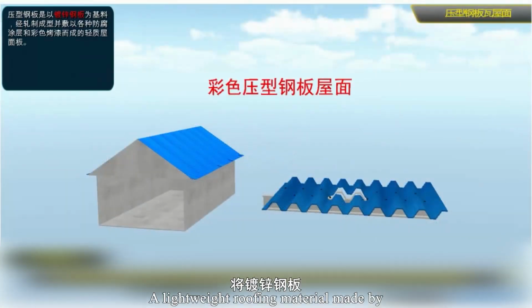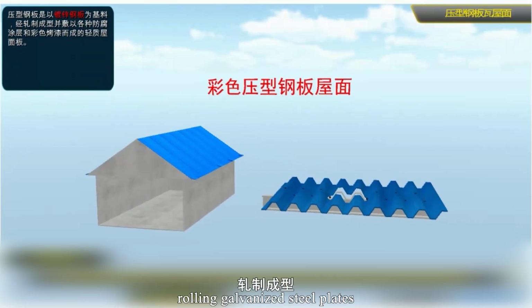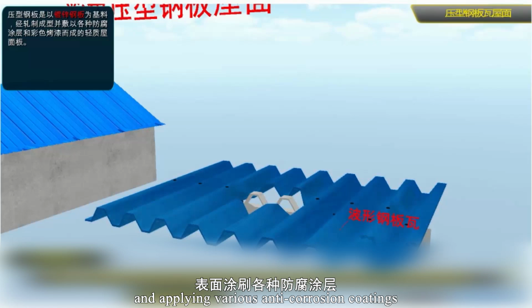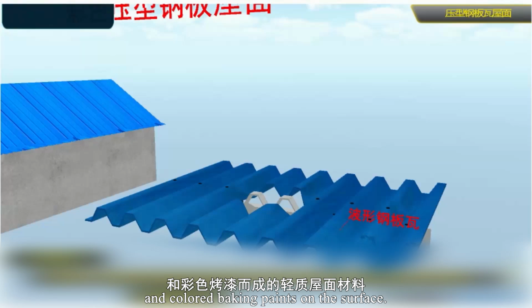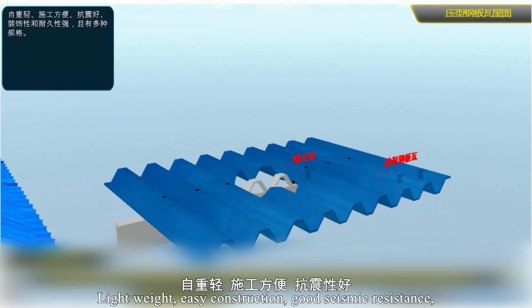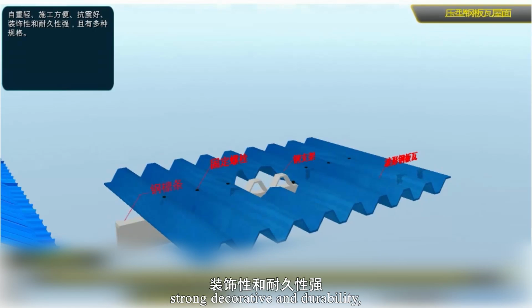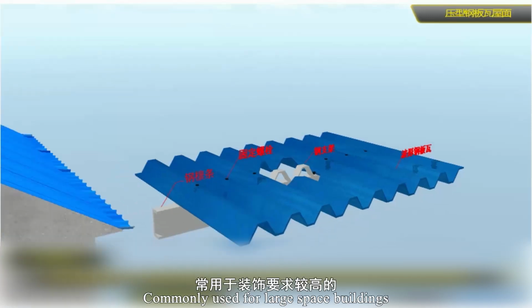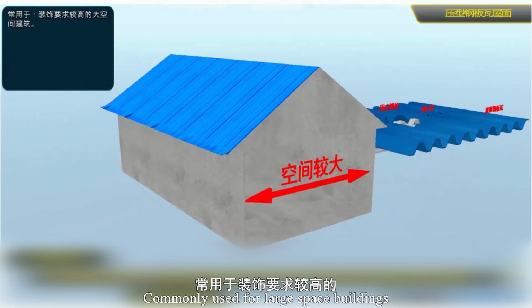Profiled steel sheet roof. A lightweight roofing material made by rolling galvanized steel plates and applying various anti-corrosion coatings and colored baking paints on the surface. Lightweight, easy construction, good seismic resistance. Strong decorative quality and durability, with multiple specifications. Commonly used for large space buildings